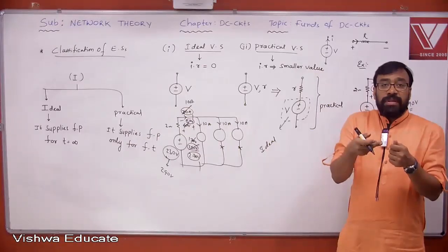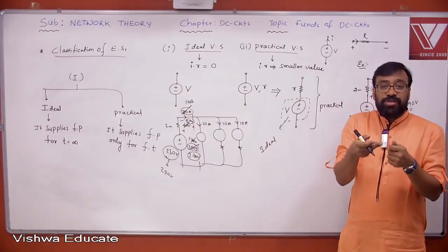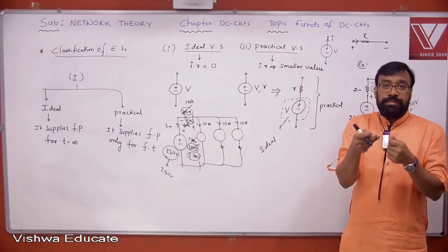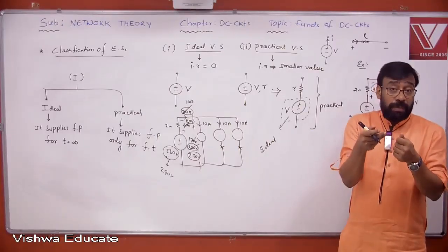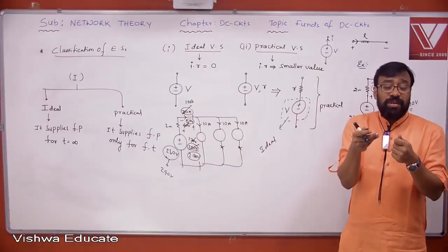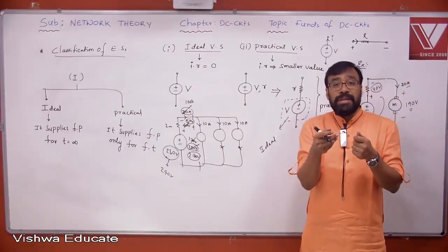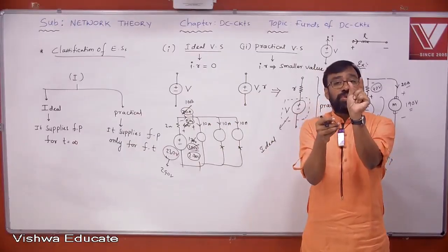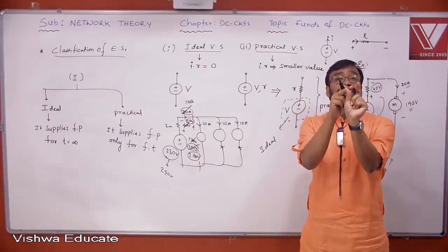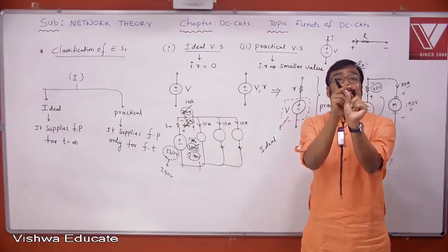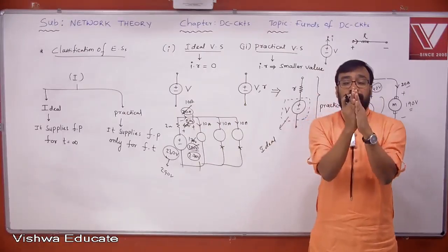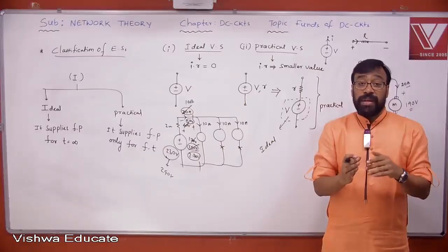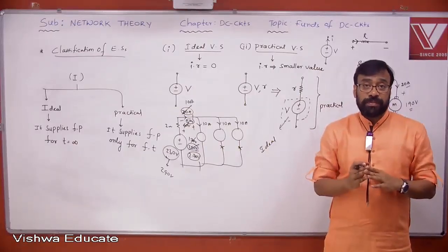If a high voltage is applied across that insulation, then that insulation may break down. Once the insulation breakdown takes place, the positive and negative terminals will be connected. The bulb has positive and negative, and in between you have an insulation. If high voltage is applied, that insulation gets punctured and plus and minus are joined, then what will happen? It leads to a short circuit. Then it is a disaster for the entire system. You understand, all of you?